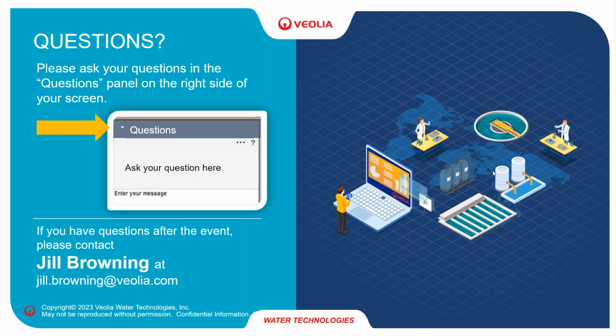Great. Here's another one, a little bit more specific regarding a project, it looks like. They are mentioning that their current feed water has 90 ppm of silica, and can they use this system without scaling? And right now, their recovery is only, unfortunately, at 50%. So you're doing about a twofold concentration at 50% recovery. So you're taking it from 90 to 180. So yeah, I think this would be something we could look at.